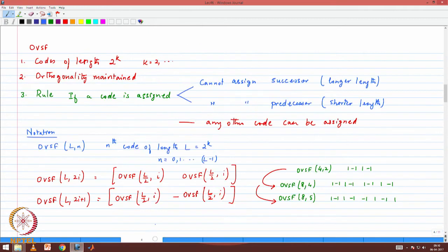Okay, another point to reinforce from our discussion yesterday, the difference between CDMA2000 and wideband CDMA. The chip rate that we were using is 1.2288 mega chips per second. All channels must have this chip rate. The occupied bandwidth of the CDMA2000 signal is 1.25 megahertz, so that's how the channelization is done.